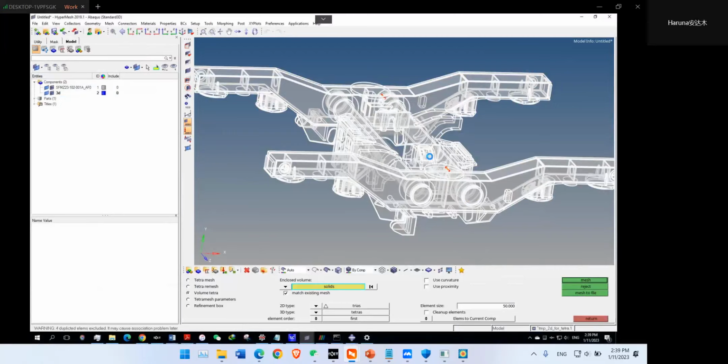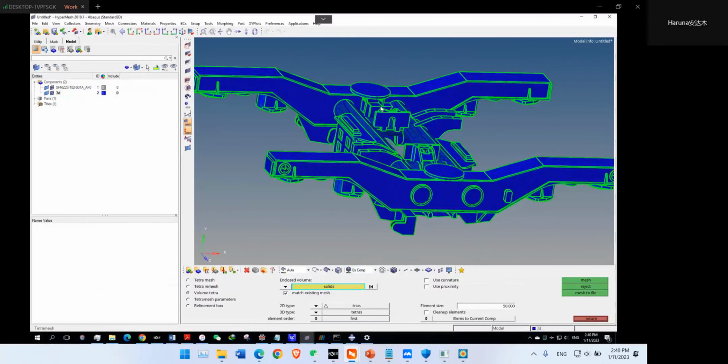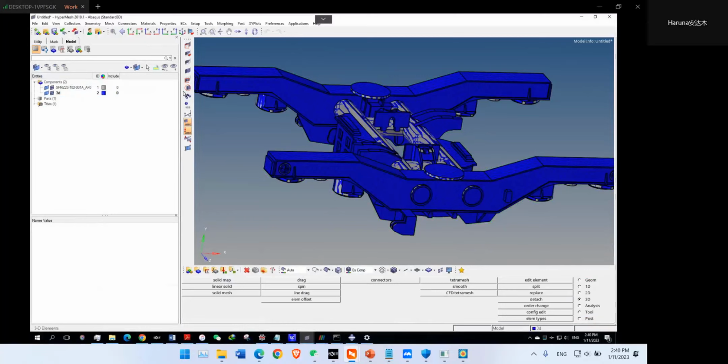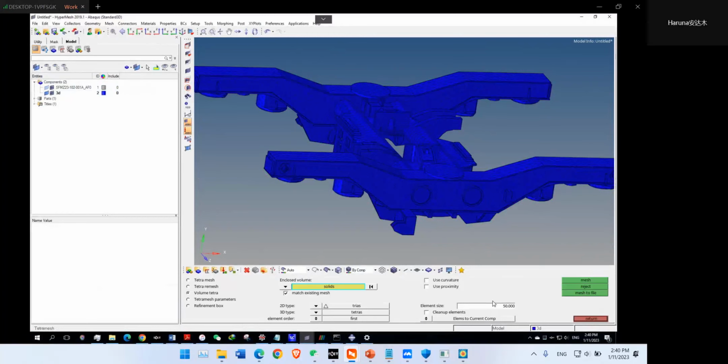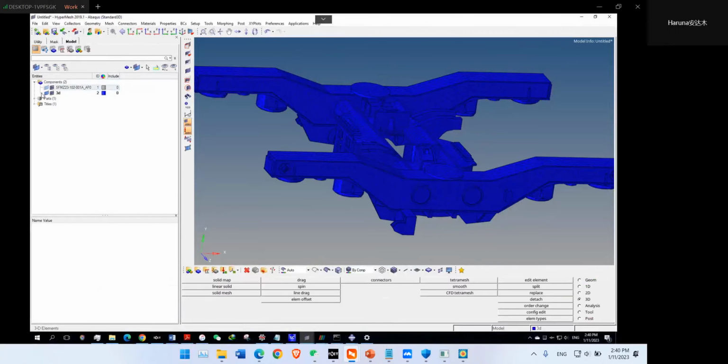One thing we should know is that the Abaqus software can actually do all this meshing for us. But the reason why I'm using HyperMesh is because when performing the SFEM simulation, we need an identical mesh so that we can compare our results for both of them. So we have our 3D mesh. Sorry, I forgot to tell us to specify our mesh size here. We have to pick a reasonable mesh size to mesh the geometry. Then I think we are done here.